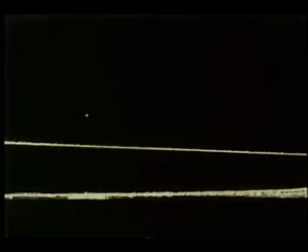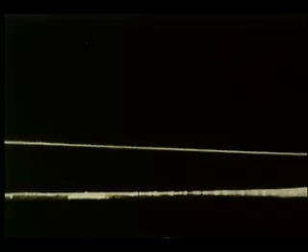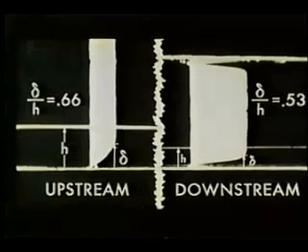It is as though a new boundary layer were being generated within the old. The combined profile at the exit is relatively thinner because there has been little time for growth of the new boundary layer by viscous diffusion.